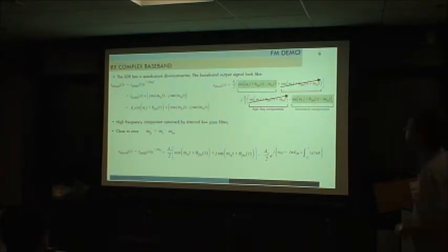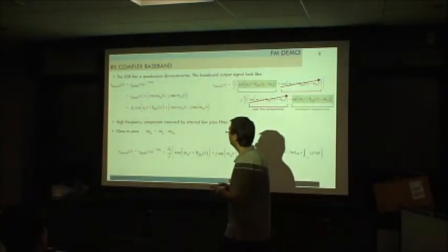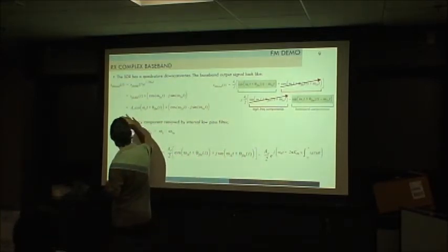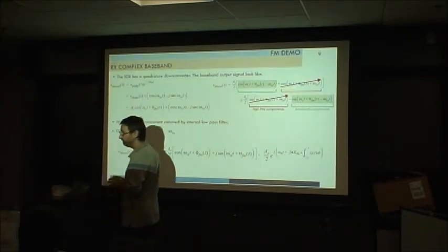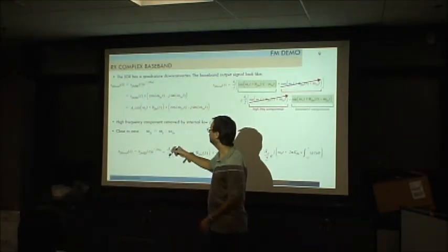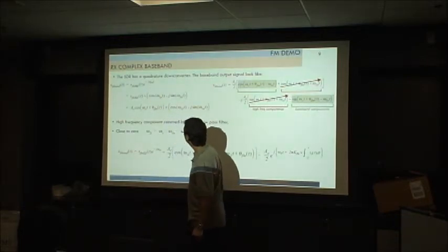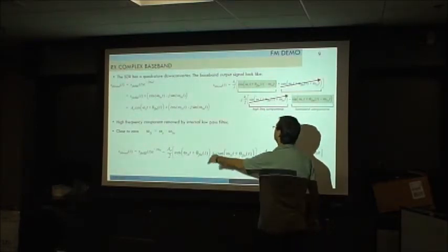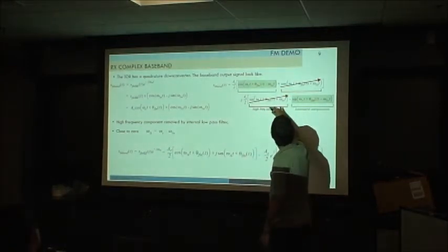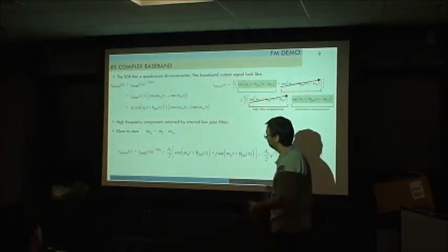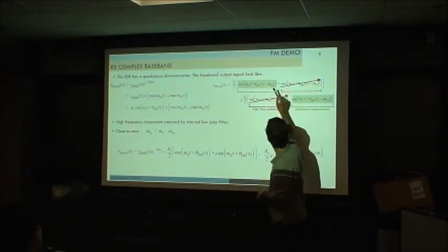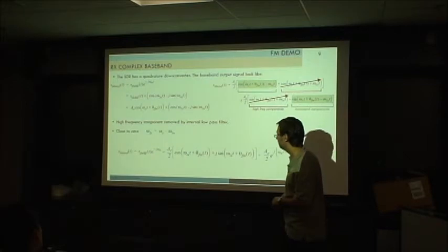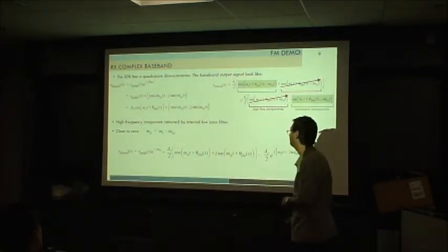So we will try to continue on that. What we are sending through the, let's say, SDR, USRP, or whatever, will be this signal, but remember that we are sending on quadrature, okay? So we have to multiply by this complex representation there. So at the end, what we are sending is this, okay? If we do the math on that, and go through the low pass filter that we have inside, we cancel the high frequencies, we can get these two green guys, okay? That is something that I placed here.